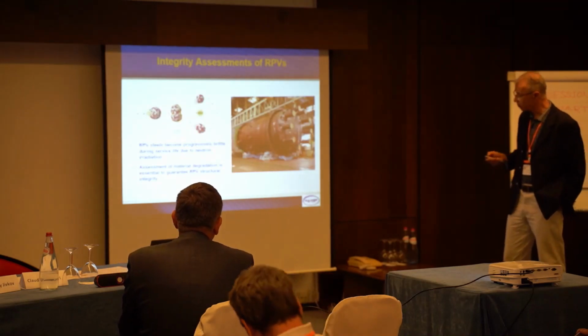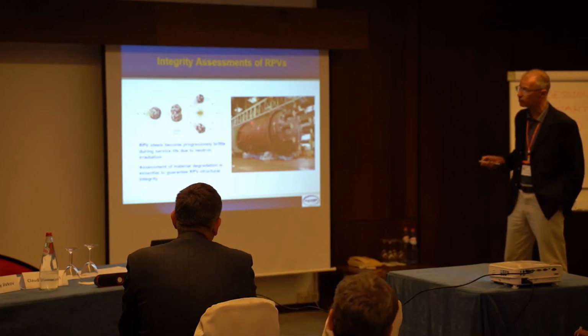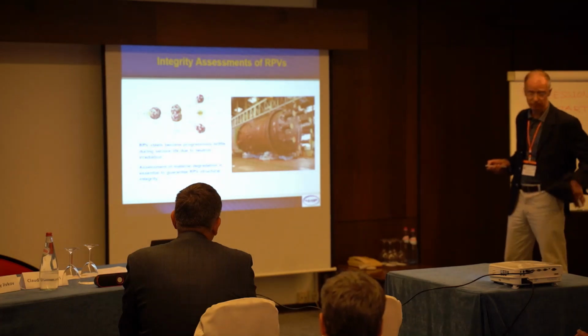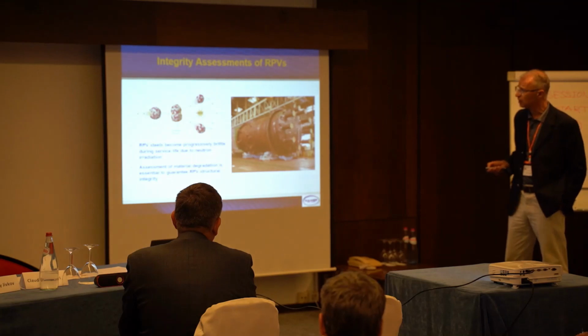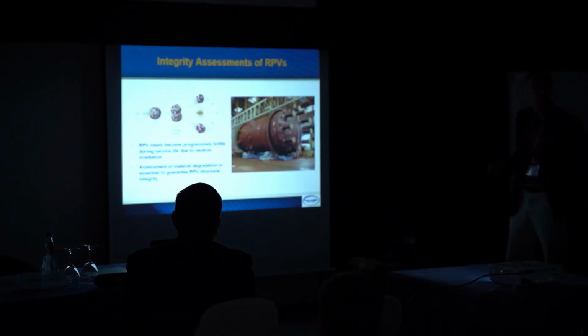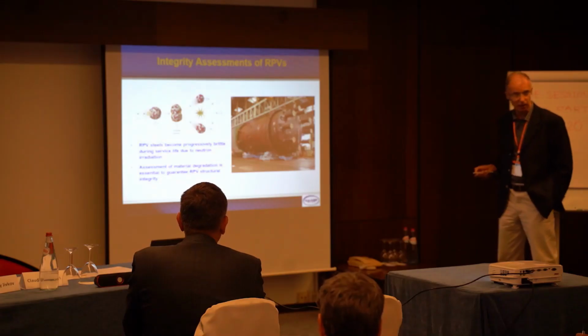Okay. So very briefly, that's the issue with the integrity assessment in reactor pressure vessels. The steel becomes progressively brittle because of neutron radiation, especially fast neutron radiation. So the assessment of material degradation over its operational life is essential to guarantee the structural integrity.